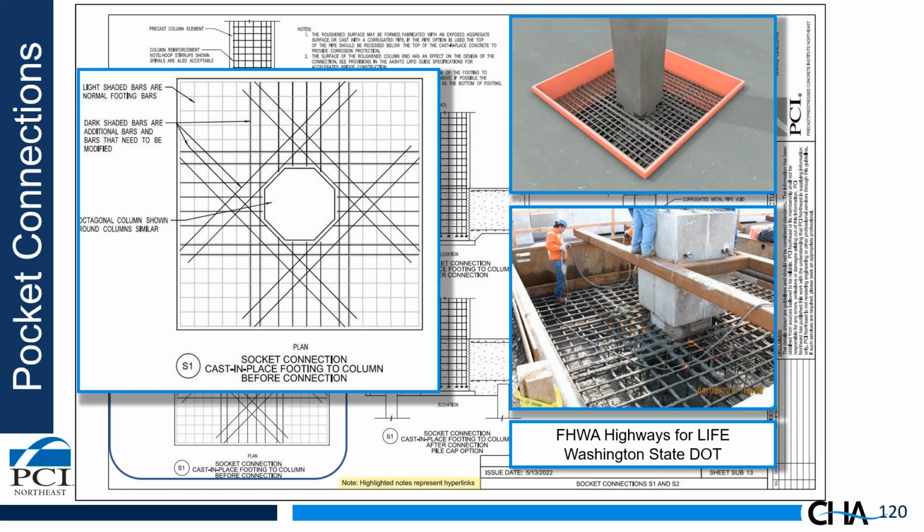What's great about this is the contractor can pre-tie the reinforcing in the footing ahead of time and simply set the column down on a leveling pad and pour concrete immediately. So it's a very fast construction, great for high seismic, and it's simple, easy to build.